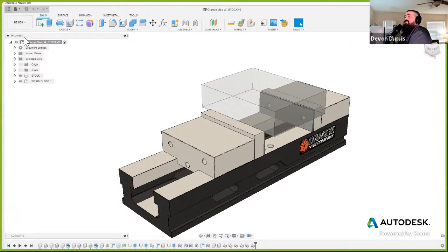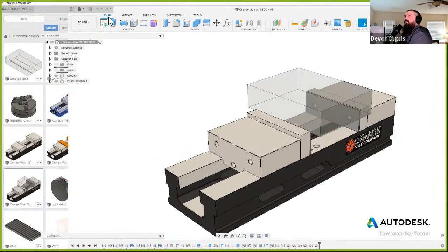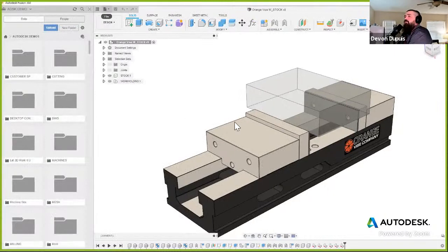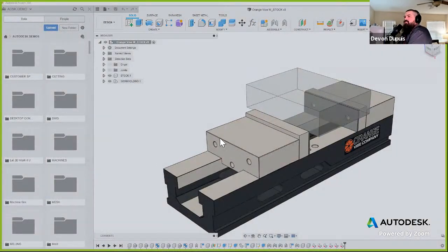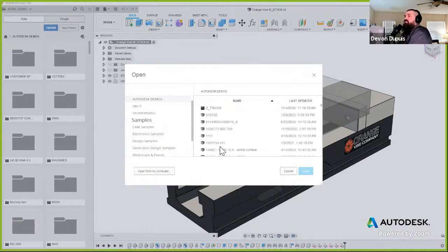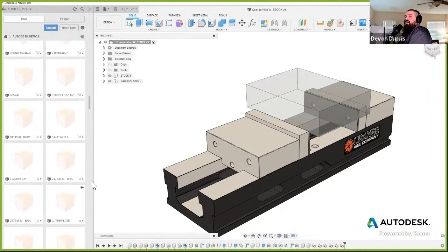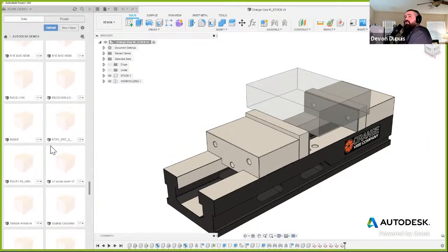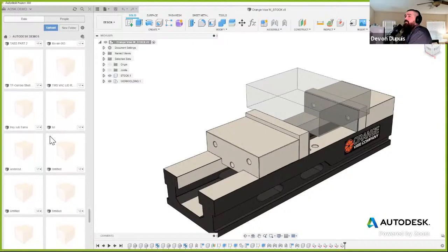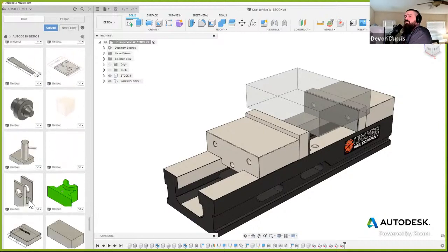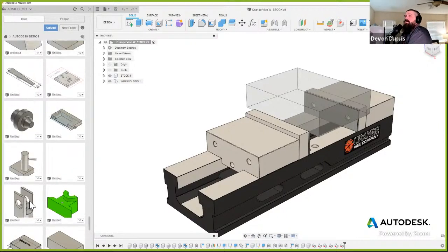All we'll do here is open this data panel, and this is probably the best way to open a file. Like I said, I see a lot of people go through here and go to File, Open, and try to look through here for the parts they're working on. But you'll see, if we get some parts in here, we might have a bunch of untitled files. I don't know what any of these are just by looking at them. I could certainly guess by looking at the date, but depending on how you have them sorted in Fusion, and that same main file here, if I scroll down, we'll see that I can see all these untitled files and what they are. So now I can say, oh, that's the one I want to open. It looks like my object. And this is a little bit better way than just using that regular file open.